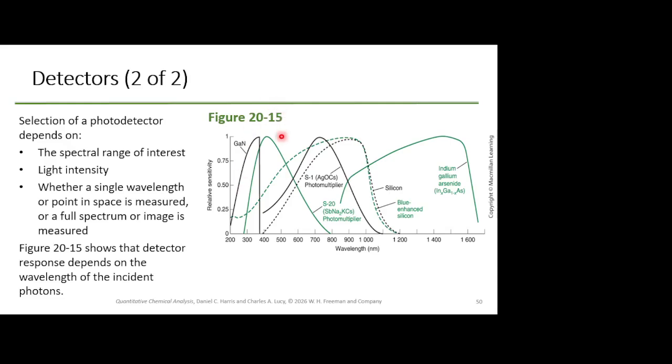Now, when we're talking about this photodetector, that material is going to dictate the proportion that's going to come off in terms of the electrical flow, that current, versus the wavelength of the light that it's detecting. Okay? And so it's going to have these major things of what photodetector is going to work for what region. This is why you typically don't see an instrument that works with UV, vis, infrared, near infrared, all of those at the same time. You can see portions of that.